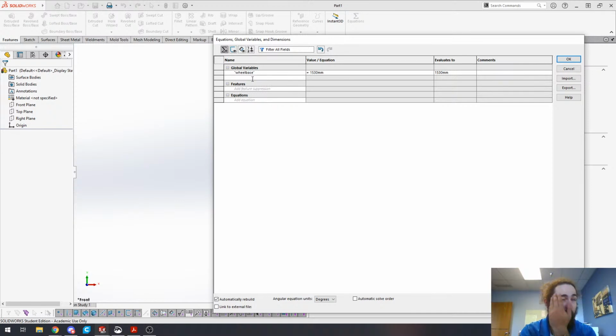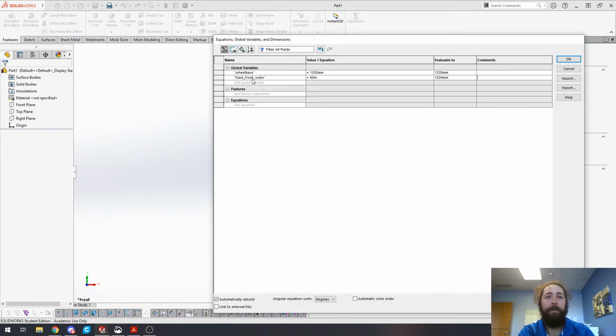Then in my case, what I did was I set up the outer track of the wheels. In our case, a constraint was we wanted to fit our car inside of a U-Haul trailer. So we wanted it to be 60 inches from the outside edge of the tire to the outside edge of the other tire. So we started with the track in the front, and it was the outer track. And in this case, we had exactly 60 inches. And same thing for the rear.